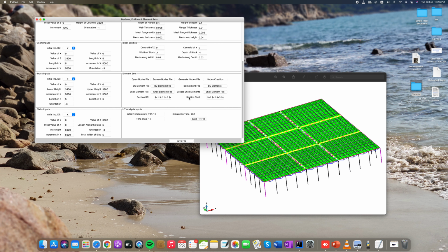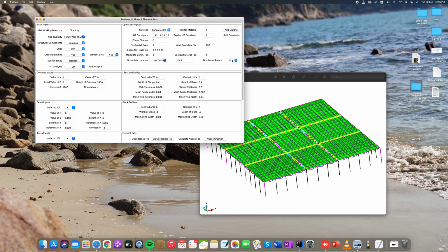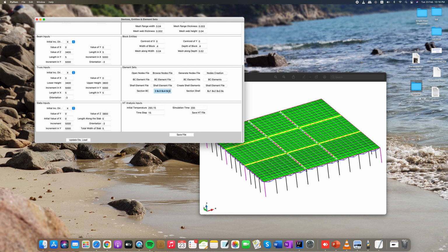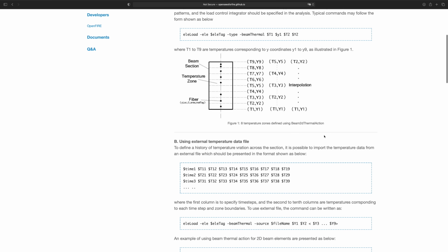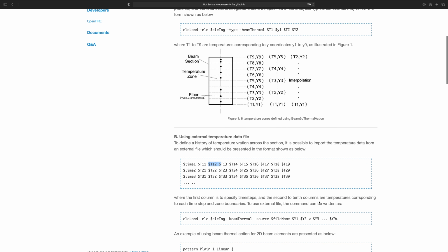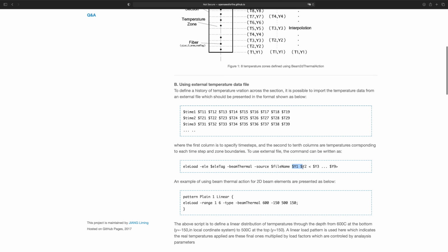This is again an input you have to provide by default, like C1. Depending on whether you choose 2 points, you will give 2 values like $ sign C1. This is a variable for your sections, for example these sections which you're defining. If you are providing 5 locations, you have to give 5 values for the locations where you are putting the temperature data.